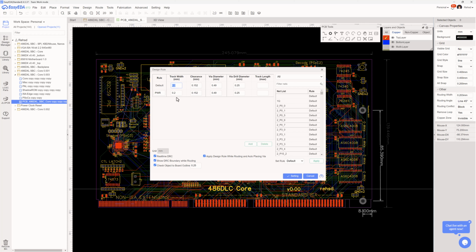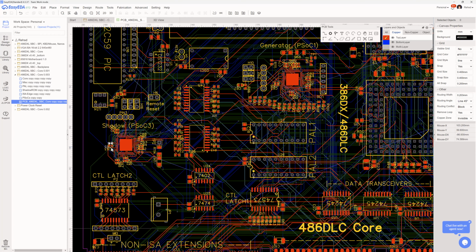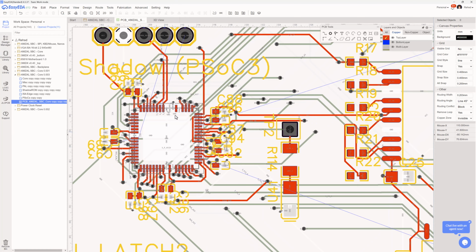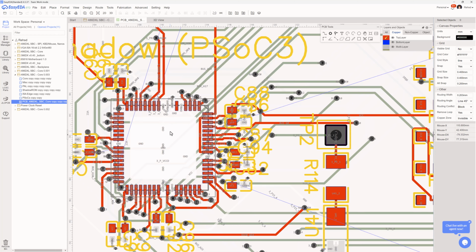It seems like I should be fine going with this type of trace width and via diameter and via drill diameter. But I'm definitely curious from many of you if you think this is an unwise type of change for this entire PCB. So if these PSOCs are going to have that challenge, the trace right now, its width is pretty much the size of this pad here coming off of each of these.